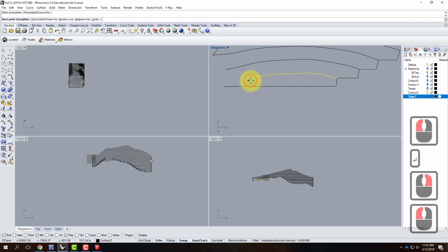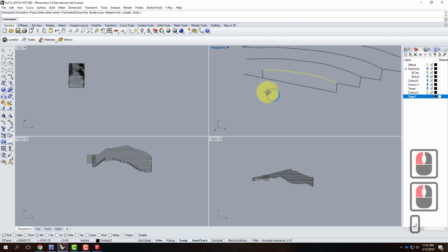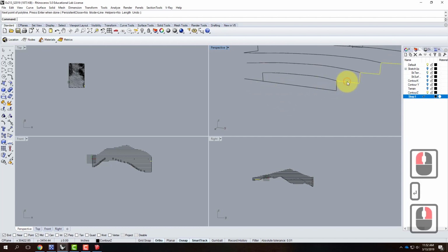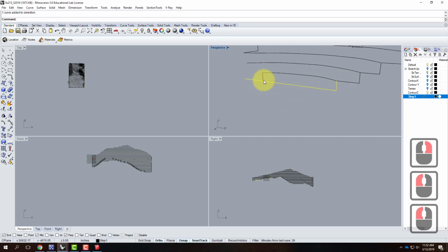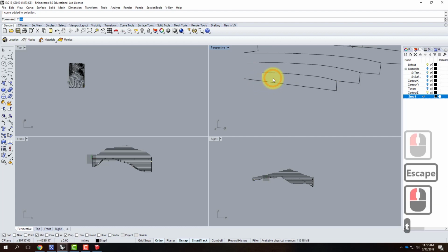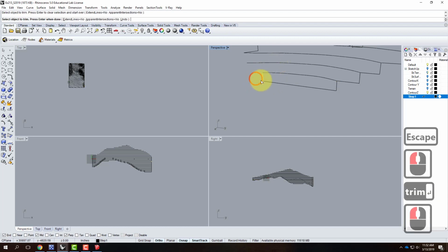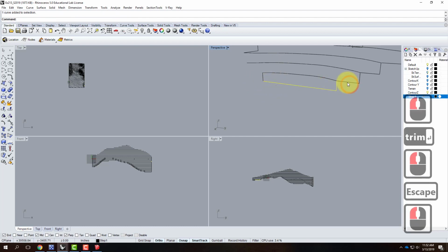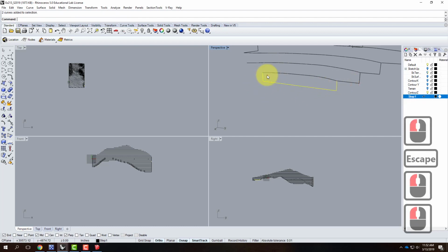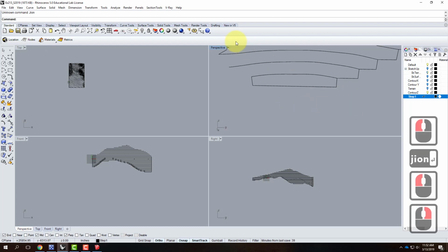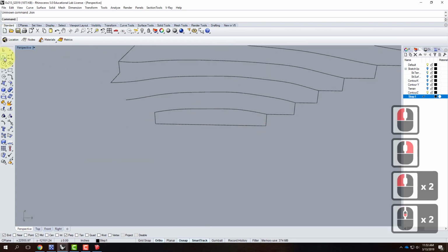And then I can start at this point and come down to perpendicular, like that. And so we can see the step coming down. There's the step. I'll trim off this edge. Alternatively, I could use a fillet and that then creates this horseshoe at the bottom. So I'll go ahead and join those together. There it is, and we can keep working our way up.